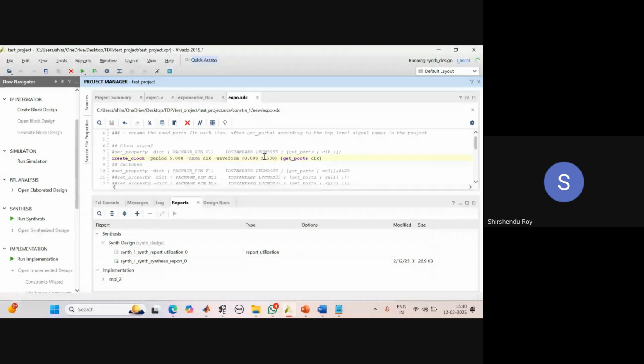But what is important is how to find the FPGA performance and how to optimize. That is very important. What are the parameters we should target that we should know? The first parameter is accuracy. We have to maintain that accuracy should be good. Then area we should try to optimize. Then latency also you have to check. Throughput doesn't matter here because we want one data per clock cycle only. Latency matters, that is, how many clock cycles later we are getting the output.